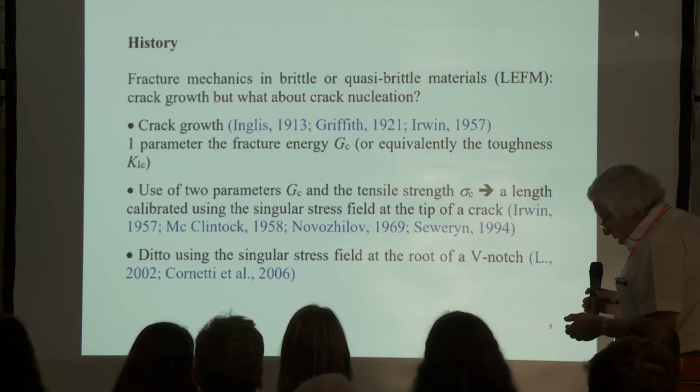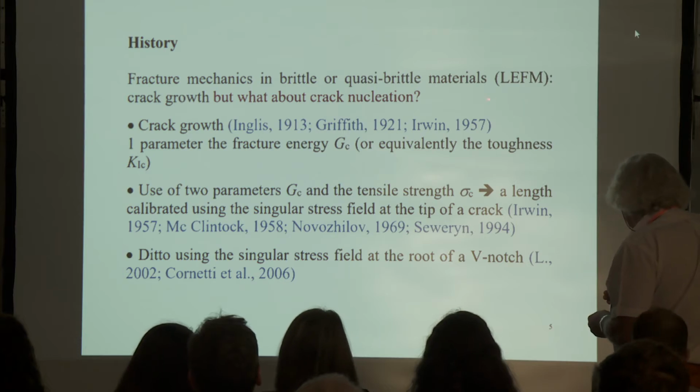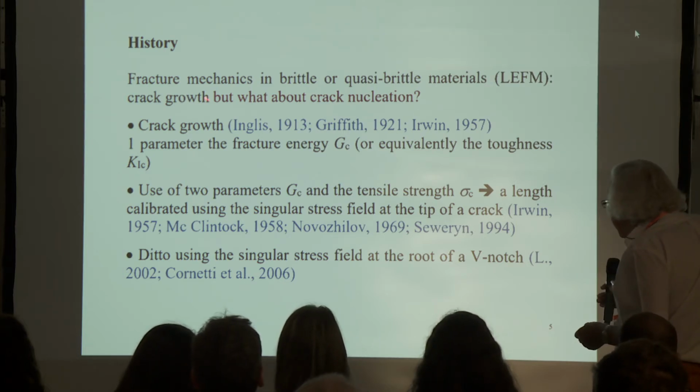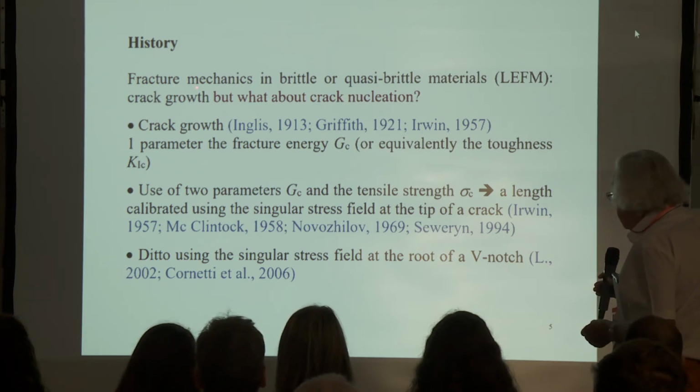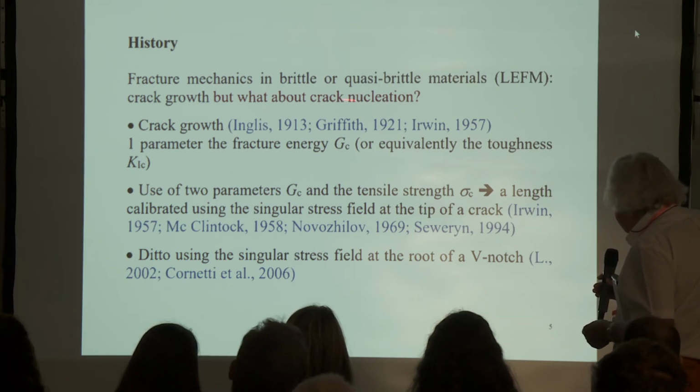Okay, a little of history. We start, of course, with linear elastic fracture mechanics that deals with crack growth. You need to have an existing crack, and you study the ability of this crack to grow or not, but nothing is said in this theory about crack nucleation.